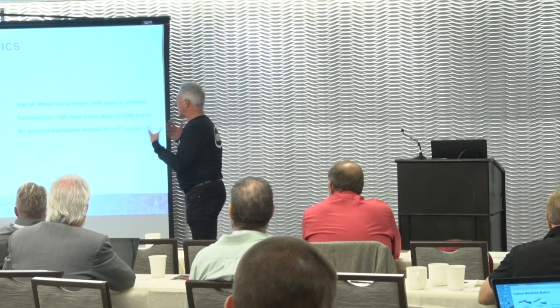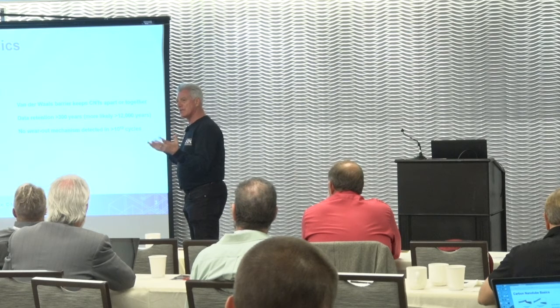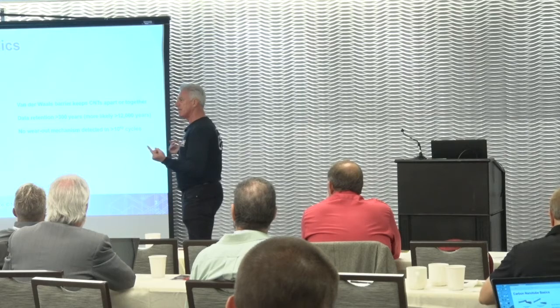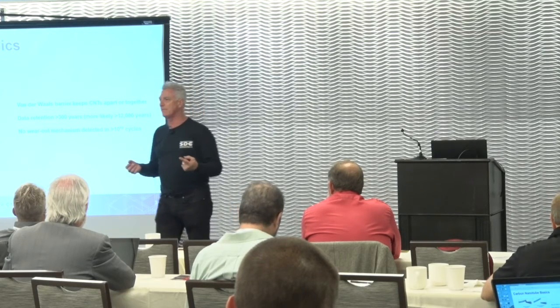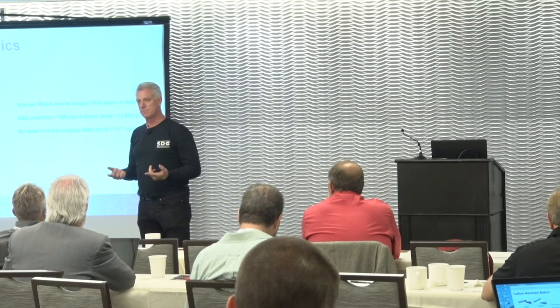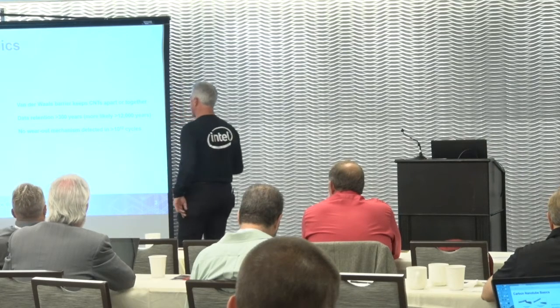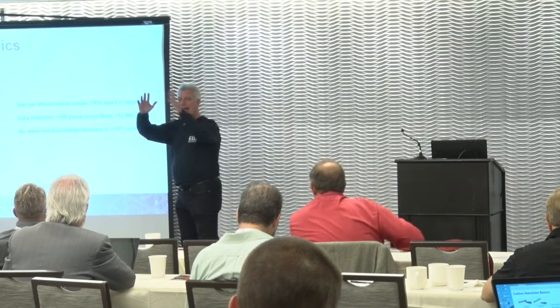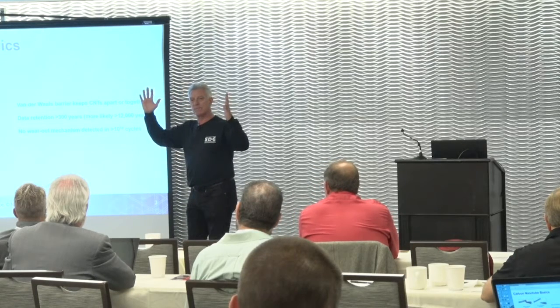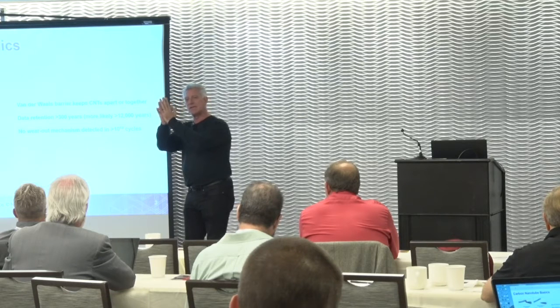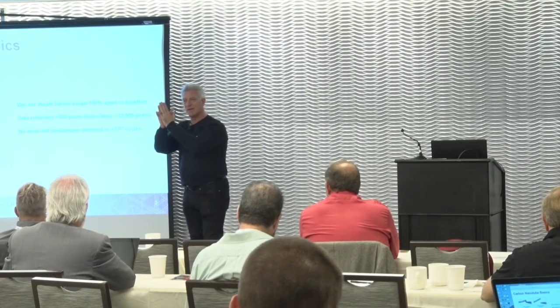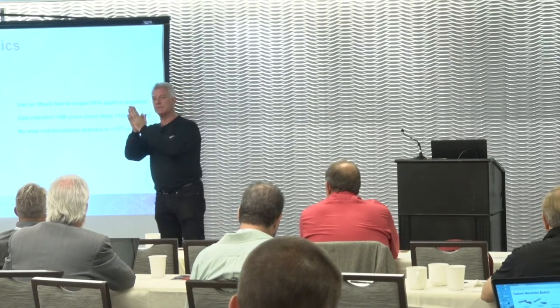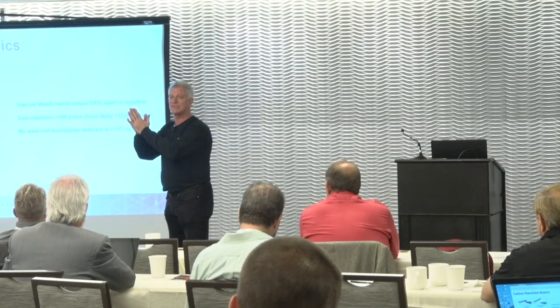So what happens is with these carbon nanotubes, the effect that we're going to take advantage of is something that you may remember from your physics class. It's the van der Waals barrier. The van der Waals barrier is that energy barrier that keeps atoms apart when the atoms are apart. And then once you cross the van der Waals barrier, it's what keeps atoms together once they're together. That distance for carbon atoms happens to be 1.7 angstroms.